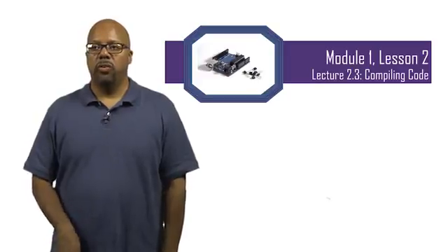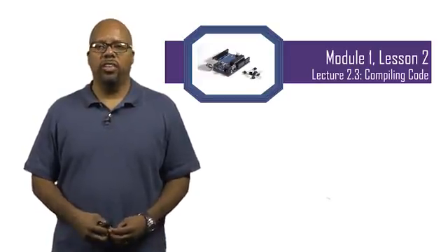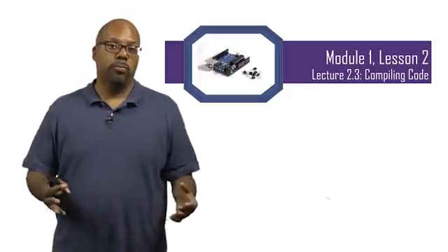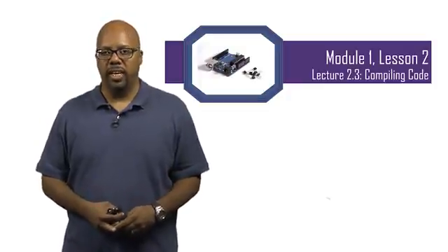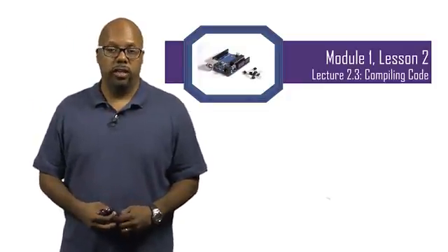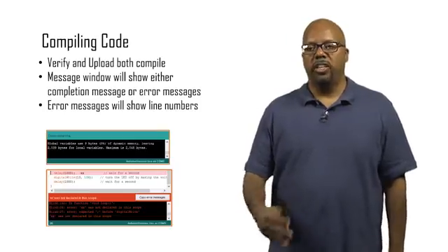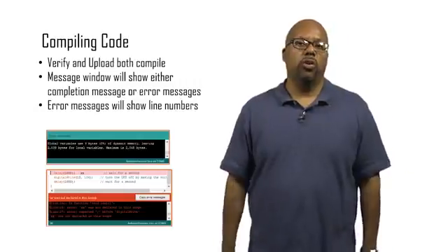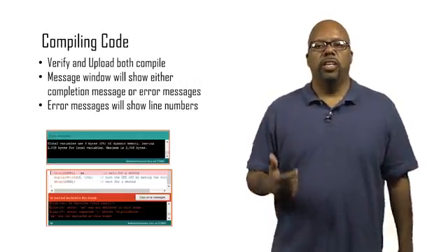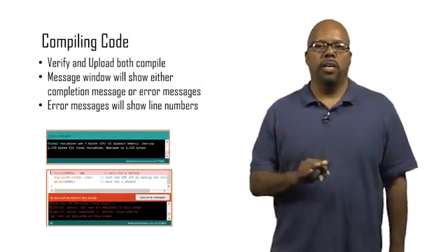In this lecture, we'll talk about how you compile and upload using the IDE, what it looks like, and what errors look like, which you will most likely see. So compiling code. If you want to compile the code, cross-compile technically, you can either verify or upload. Those are both buttons, verify and upload.